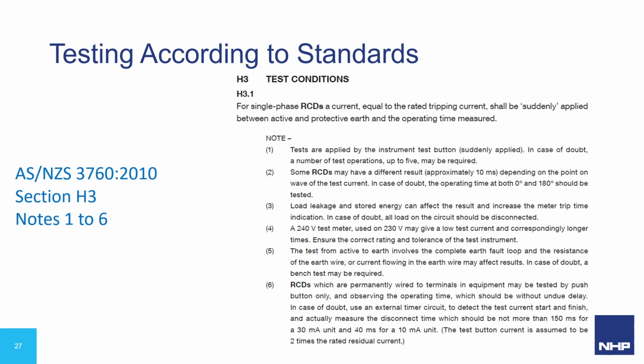These included observation of the rated voltage of the test equipment compared to the rated voltage of the RCDs being tested, as the test results may differ if the voltage levels differ. Notes 1 through 6 are highly recommended reading for those involved in RCD testing. WHS and OHS regulations in each region basically say the same thing in the required testing procedures. Work Health and Safety Code of Practice